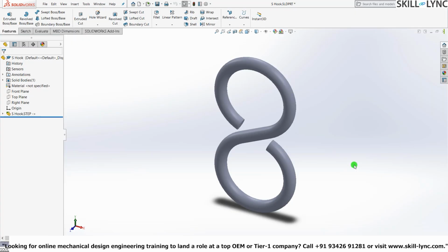Okay, we have our S hook here. So what we will be doing is fixing this area, this place, and this part of our hook, and we will be running a small stress analysis with a certain amount of force acting in this way. Then we will run a fatigue study to determine how many cycles this S hook can experience before it undergoes failure. If you're still wondering where to find this hook, if you have a chain or any gold ornaments, you will be able to find the S hook. It's normally used to hold the two ends of our chain, and it helps us to remove it and put it back. This is fairly straightforward.